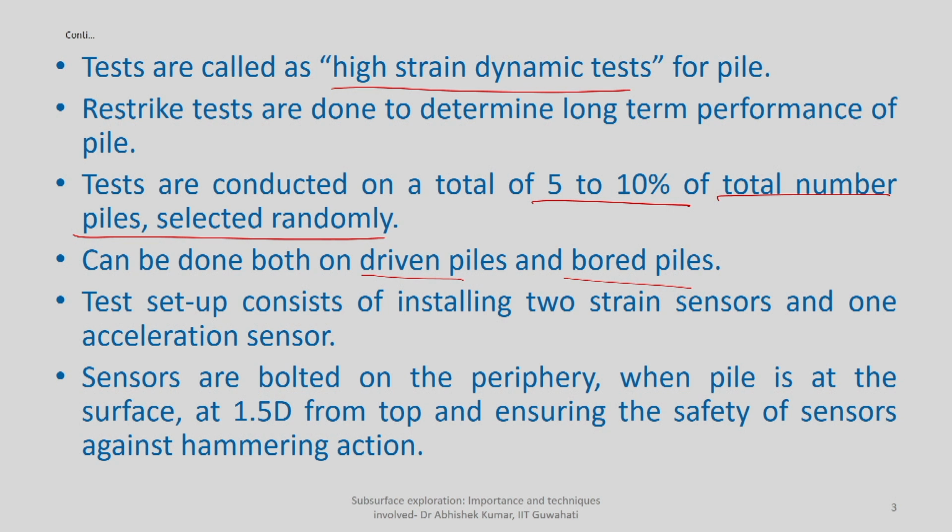Against the hammer impact, the behavior of the soil or the pile will be detected by installing two sensors, generally two strain sensors and one acceleration sensor.